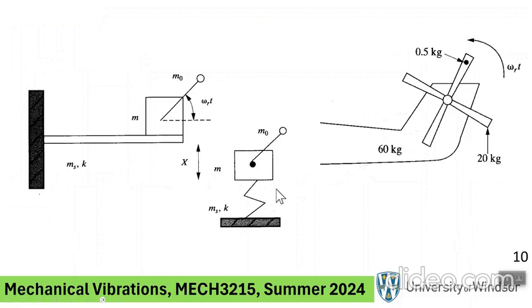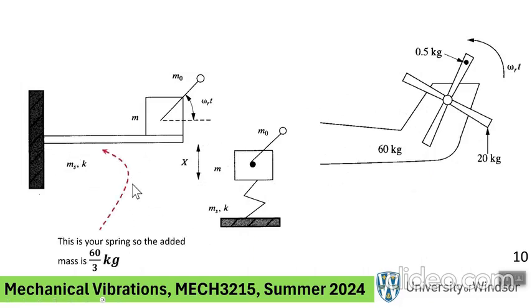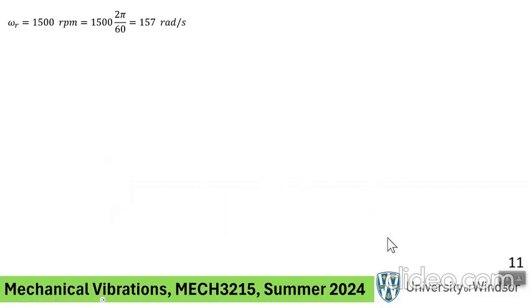Let me also say it's helpful to look at this diagram. We take a cantilever beam, pretend that the tail section is a cantilever beam. It has a mass. We accounted for the mass, 60 kilogram. And if necessary, we can calculate based on the stuff that we know about the properties of the tail section, aluminum, and then I, the cross-sectional moment of inertia, etc., and the length of it. We can estimate the value of this spring, fancy spring. Okay. But anyway, let's move on.